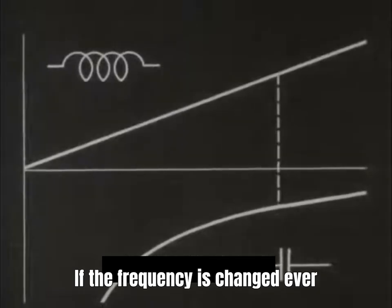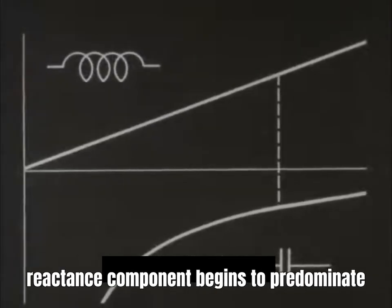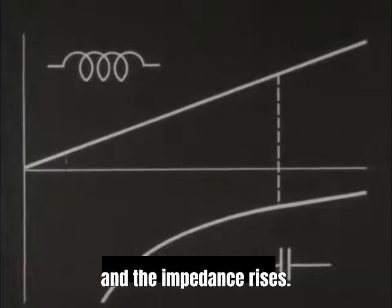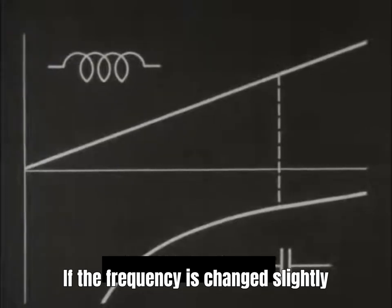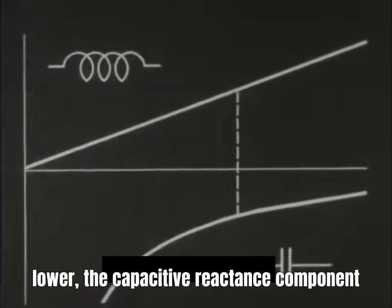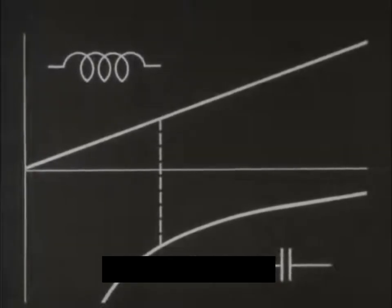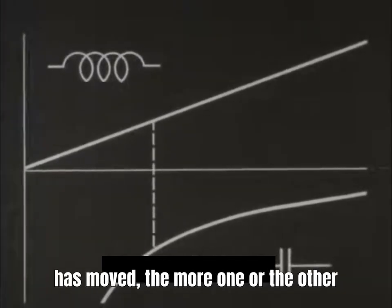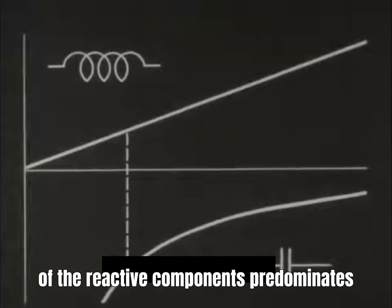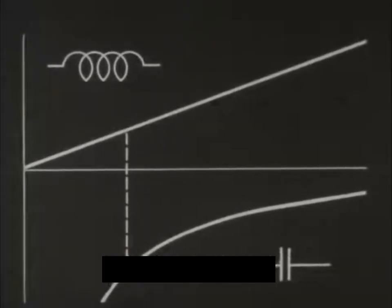If the frequency is changed ever so slightly higher, the inductive reactance component begins to predominate and the impedance rises. If the frequency is changed slightly lower, the capacitive reactance component begins to dominate and again the impedance rises. The farther from resonance the frequency is moved, the more one or the other of the reactive components predominates, and the higher the impedance becomes.